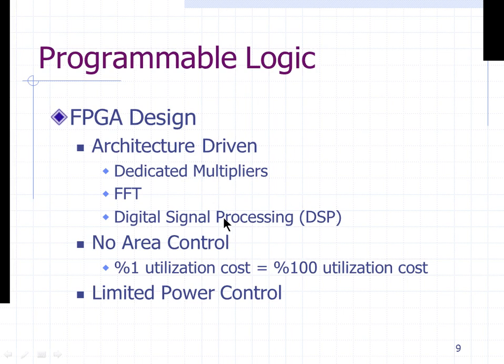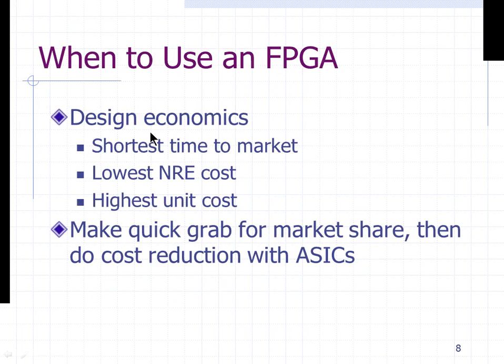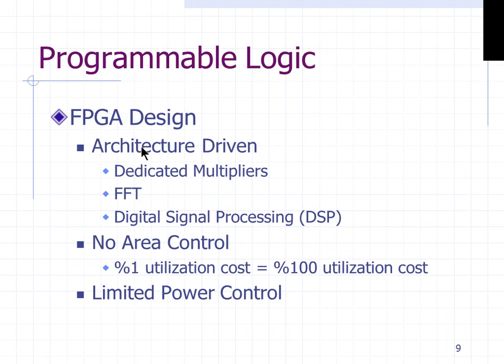But there could be other areas where an FPGA will give you better performance compared to ASICs because FPGA has a lot of parallel logic. You can develop a lot of parallel logic in the FPGA compared to ASIC design. FPGA having parallel logic and other advantages like shortest time to market can then become advantages for the product design.